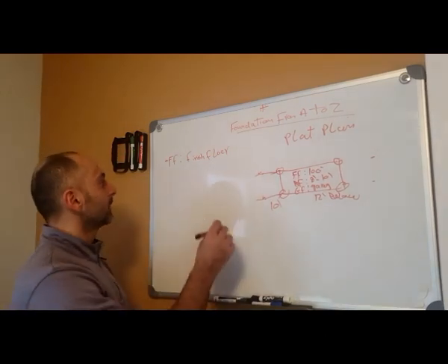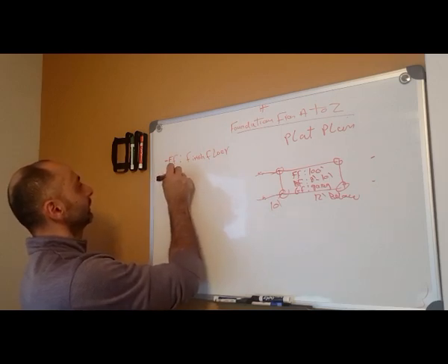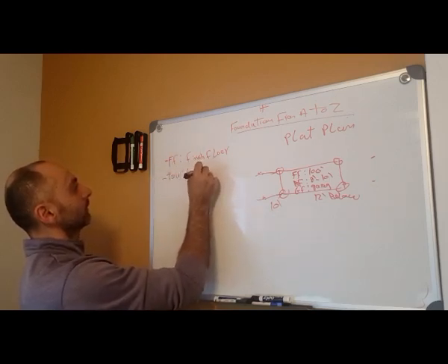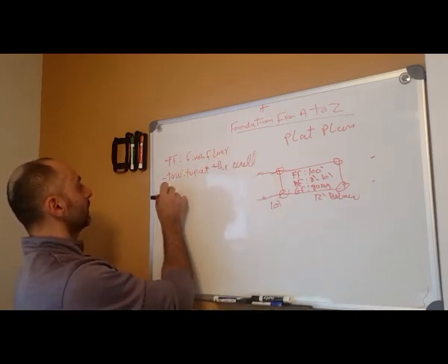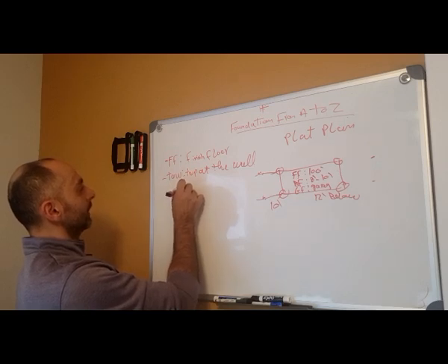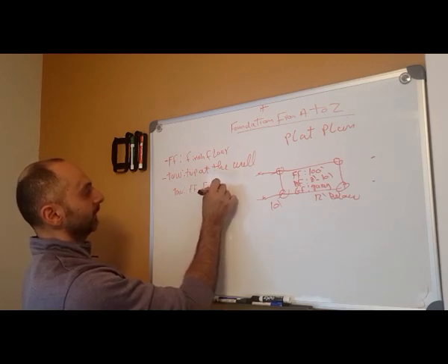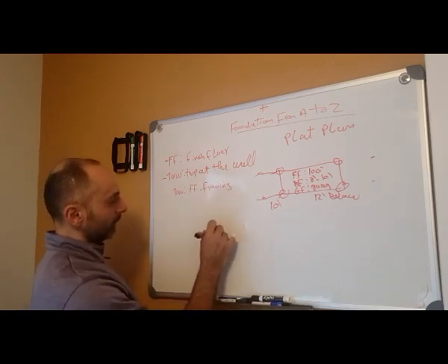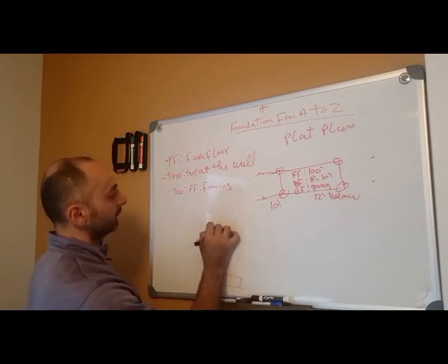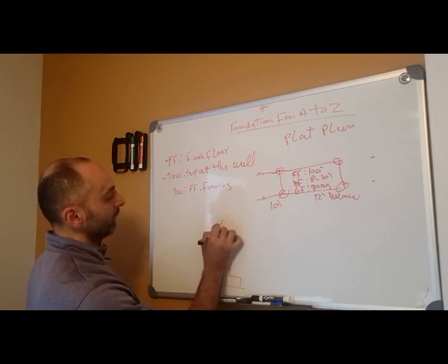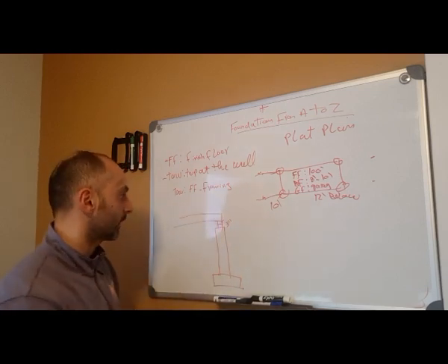Now, you also have a very important number called TOW, top of the wall. For the top of the wall, you need to take the finished floor minus the framing. That means here's your top of the wall. You're going to have 2 sill plates, which are 3 inches usually, then 2x12s or TGIs or whatever.